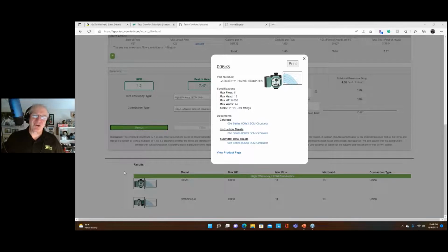Again, it's a circulator. It's working on a pressure differential. It's not a pressure creator. It's a pressure differential machine. It's creating a pressure differential within its loop to create flow. So I can't see that happening, Jesus. But again, excellent question. All righty, let's see what else we have here. I want to answer a couple more questions, and I want to look at how we would use this with a crossover valve. So let me get a couple more questions here.